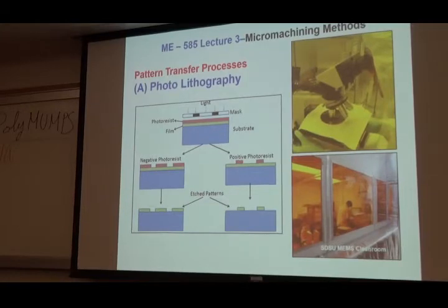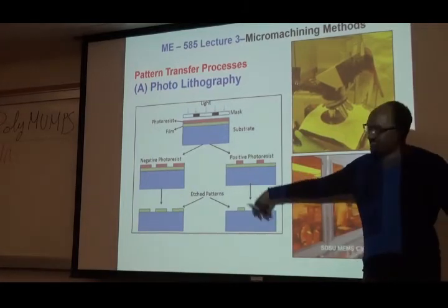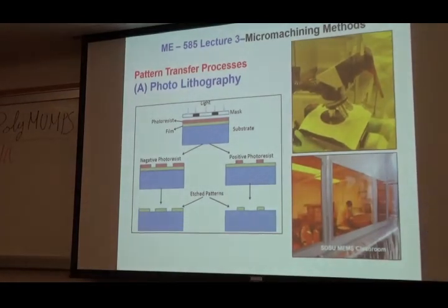Okay. So in terms of the application, when do you want it to be polymerized and when do you want it to be depolymerized? That's a very good question. Typically, what people use is a positive photoresist, for most actions. It's cheaper, and it's very easy to work with, easy to wash. You will know this when you go to the cleanroom. Because if you touch the negative photoresist, it sticks to your fingers if you're not dressed properly, and it sticks to equipment. Some labs don't like it. In fact, they banned it.